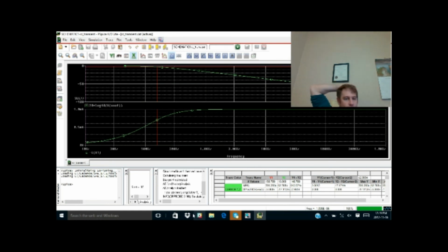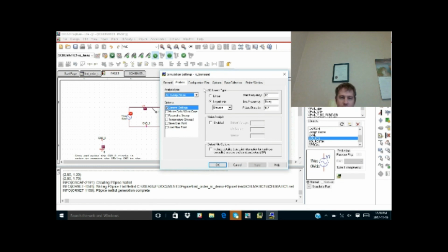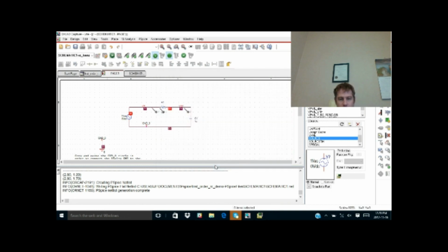Again, I just want to highlight that I originally thought this was a linear scale, but it's not. It's a logarithmic scale. You've got one decade here, another decade here, another decade here, another decade here, and another decade here. It's probably better if I cut this down to 100 kilohertz. I could rerun this to show you a little more detail on the right range of frequencies. So instead of 1 meg, I'm going to go 0.1 meg. Okay, I'm going to rerun this one more time.